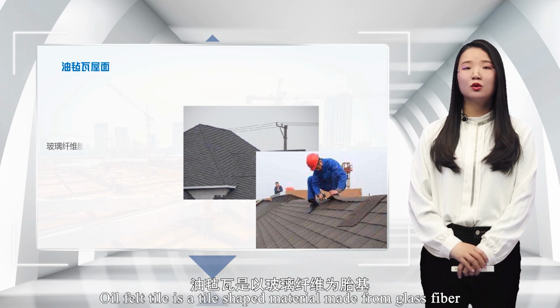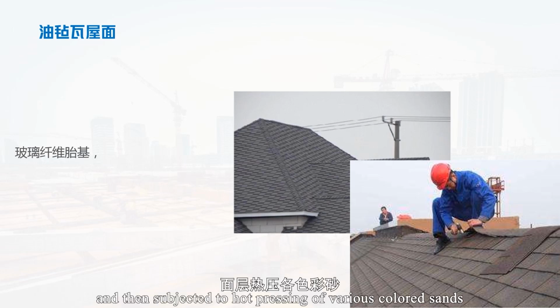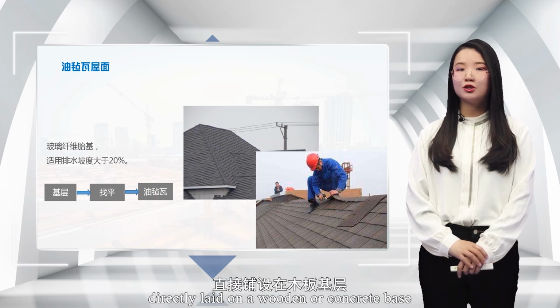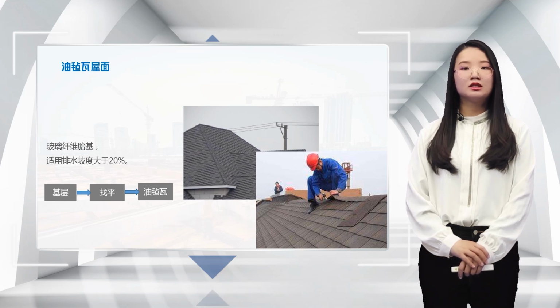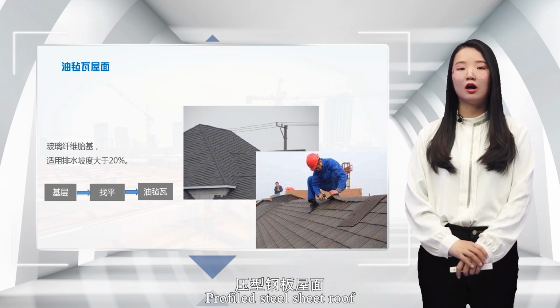Oil felt tile roof. Oil felt tile is a tile-shaped material made from glass fiber as the base material, which is coated with asphalt and then subjected to hot pressing of various colored sands on the surface layer. The back is sprinkled with insulation material, and the shape is square or semicircular. Suitable for sloping roofs with drainage slopes greater than 20%. Directly laid on a wooden or concrete base and cement mortar leveling layer. Good flexibility, acid and alkali resistance, non-fading, lightweight, waterproof.